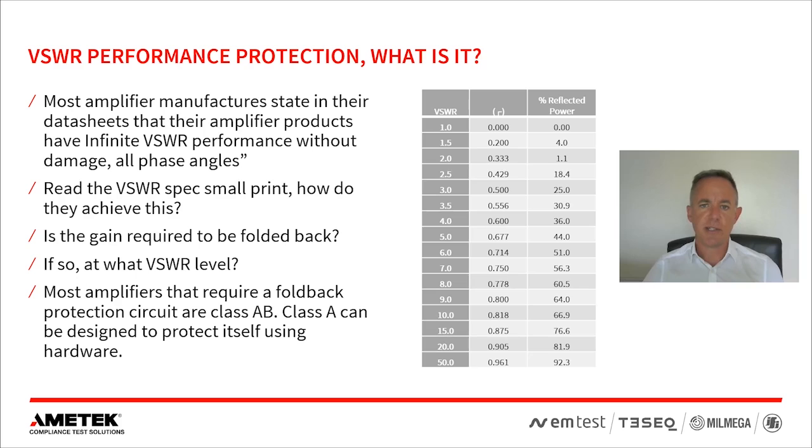Though [they] are suitable for many EMC immunity applications, one thing to be mindful of is the growing popularity of reverb chambers. These, by their very nature, generate high VSWR conditions, so Class A products are probably the preferred choice.